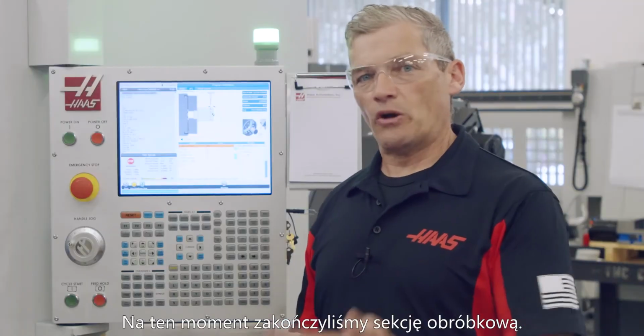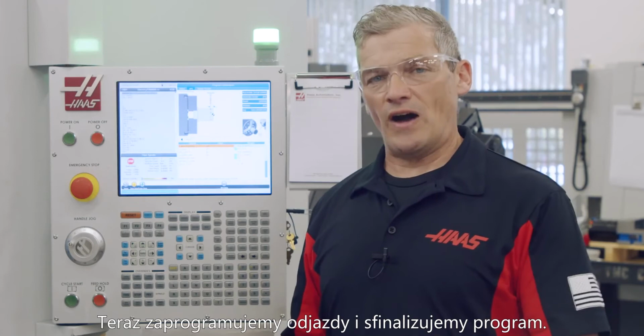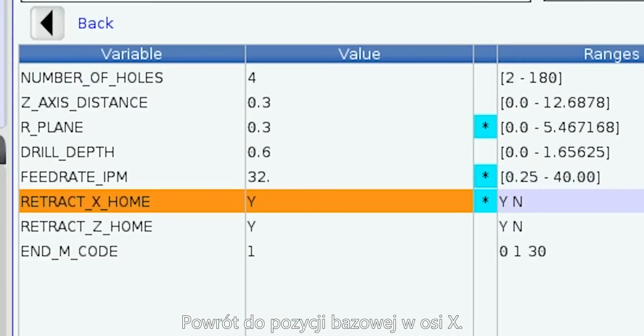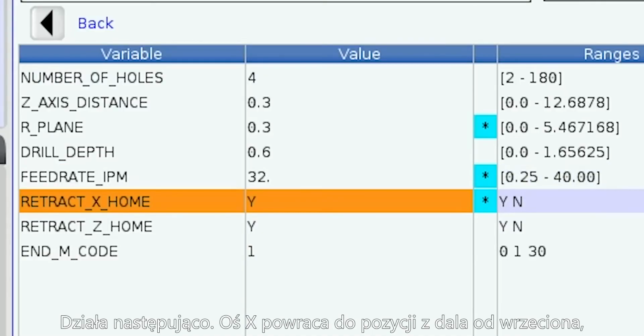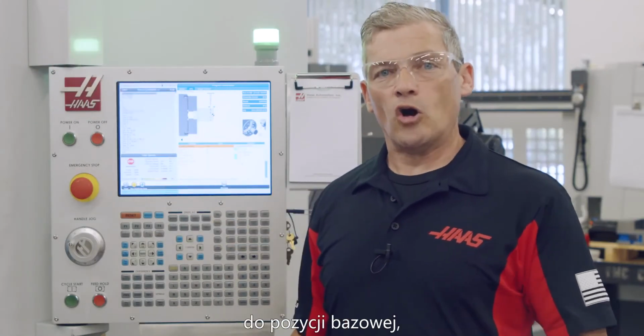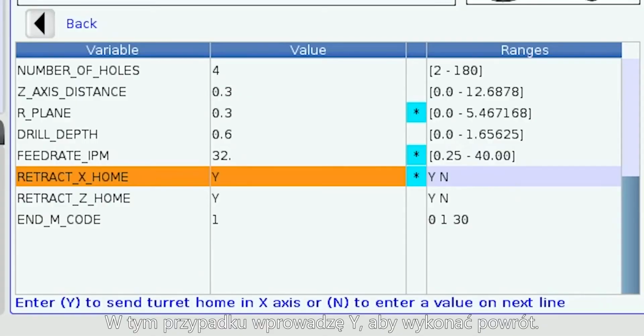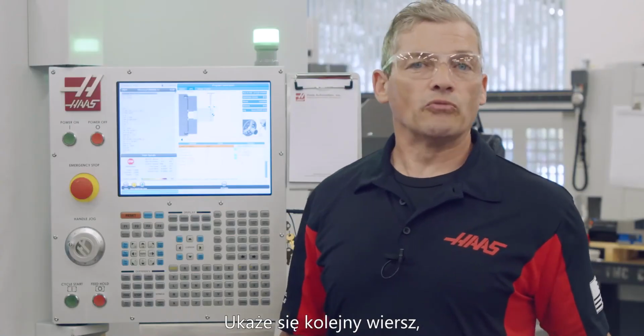Now at this point, we're done with the machining section, and now we'll just program retraction moves and finalize the program. Retract X home does just that. It retracts the X-axis upward away from the spindle all the way to home position before the Z-axis moves. In this case, I'll enter Y for yes. If you want to specify where the X-axis moves, then answer no, which will expand another row and you can define a specific position.